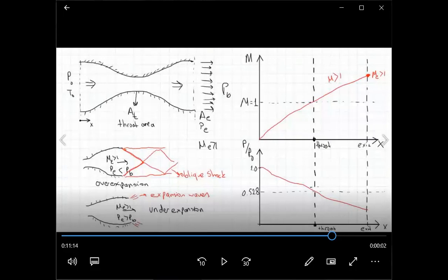But for a rocket flying more horizontally, or a fighter aircraft flying horizontally, meaning at a constant altitude, so at a constant PB level, depending on the PB level and the nozzle shape, the nozzle could be operating in an overexpanded fashion, or an underexpanded fashion, or a perfectly expanded fashion. Okay, so this is a little bit more extra information.